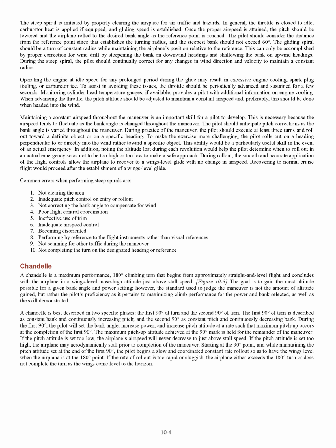Common errors when performing steep spirals are: 1. Not clearing the area. 2. Inadequate pitch control on entry or rollout. 3. Not correcting the bank angle to compensate for wind. 4. Poor flight control coordination. 5. Ineffective use of trim.